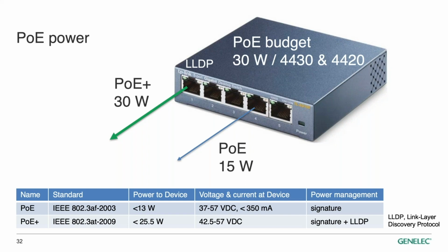And we recommend this PoE Plus 30 watt power to be used with these loudspeakers. They can operate also with the conventional older IEEE standard PoE that is 15 watts, but that is something that is not recommended or the default scenario.